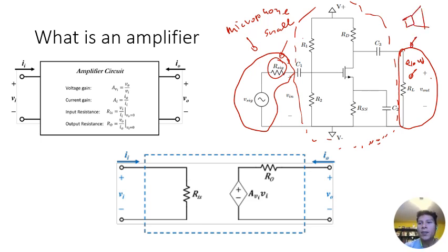Well, that's your load. Most speakers tend to be like 5 ohms or 20 ohms. You can actually look this up. If you have a speaker, it will tell you what the resistance associated with that speaker is. And so that's what you load the amplifier with.